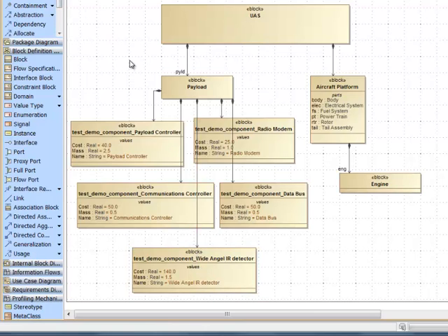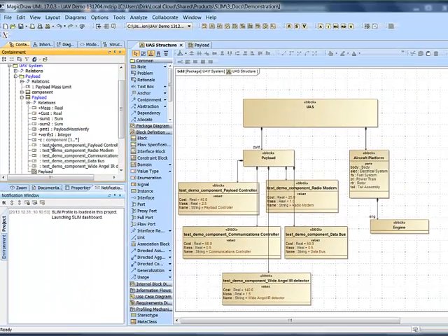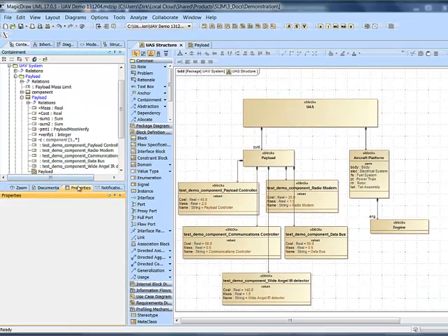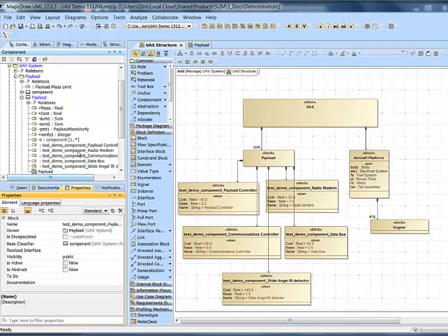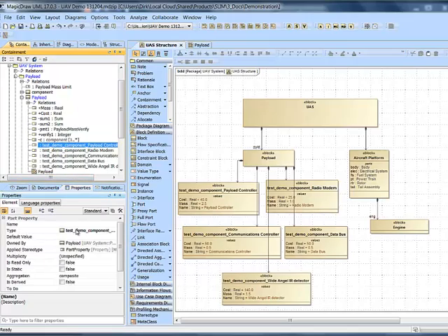So you can see that in the space of a few moments, I have created a SysML compositional model for the structure of our integrated system using existing information from a variety of different databases. Now, we have some additional housekeeping to do. For example, all of these new part properties that we've just created would probably need to have part property names.